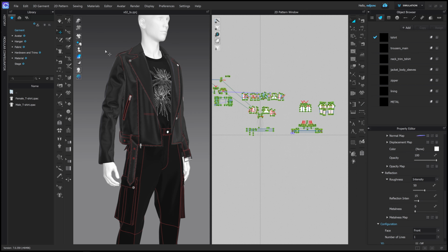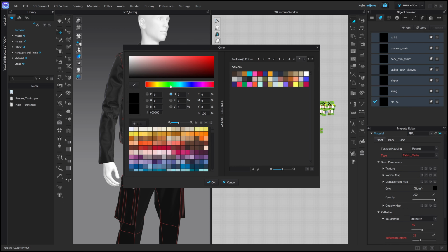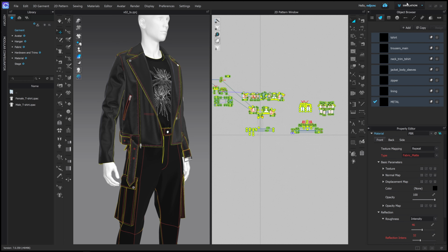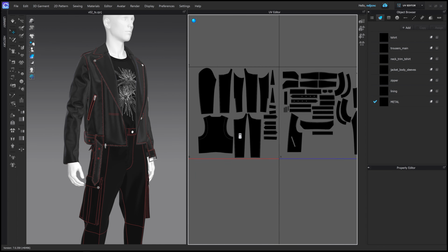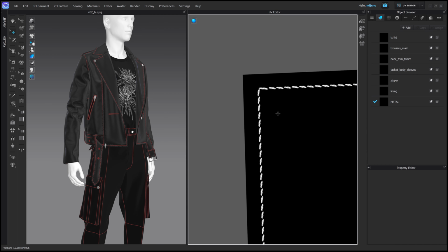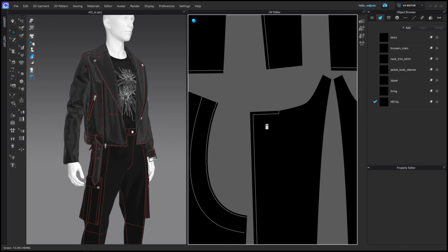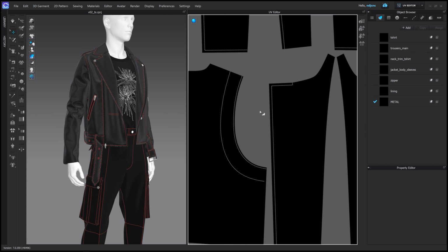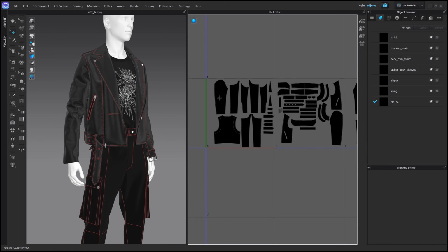And for all the base fabrics, I've selected all of these materials and set those base colors all to black, so to completely black. And the reason I've done that is so that when I look at this in the UV editing workspace, with the same UV layout as the previous file that I was in, if I zoom in now, my top stitches are visible as black and white information, and this can be used in Substance to create a height map and to create masks in order to make these stitches visible without using geometry and just by using the texturing system.